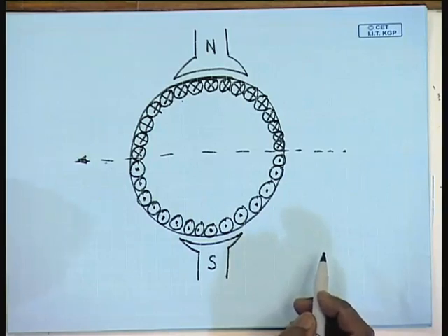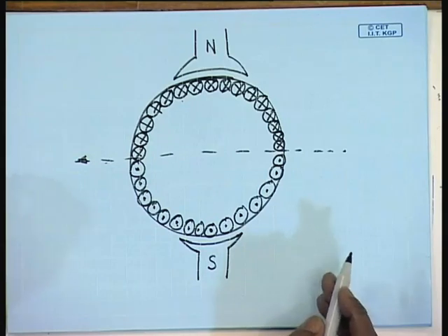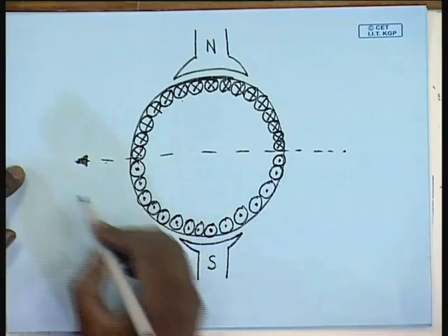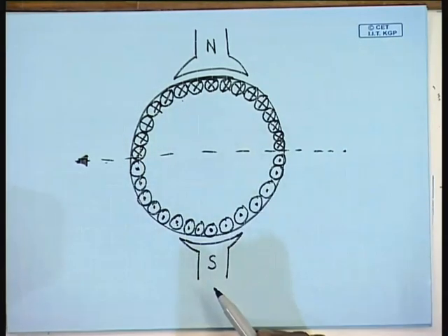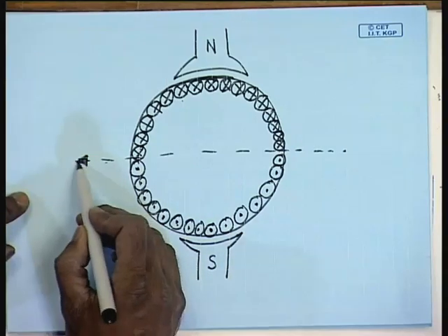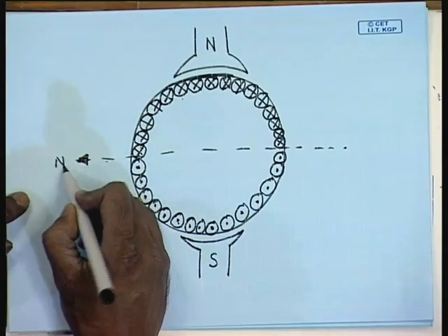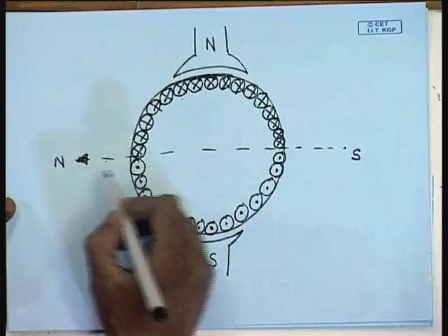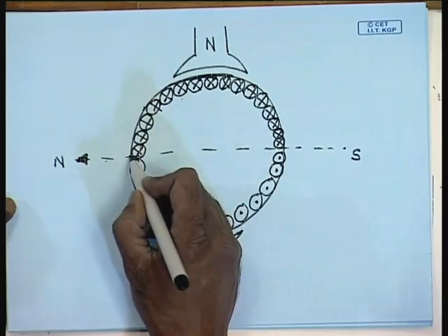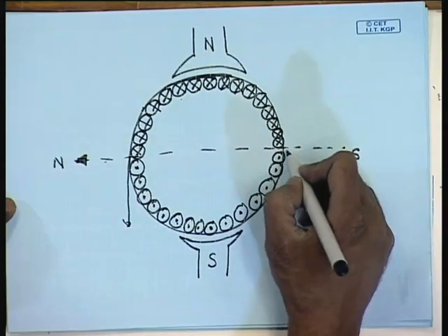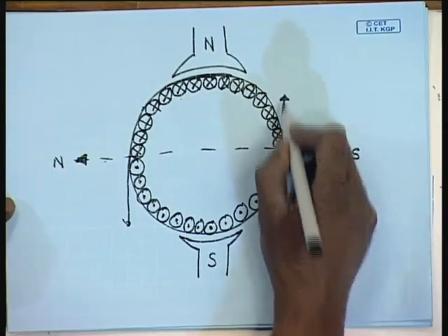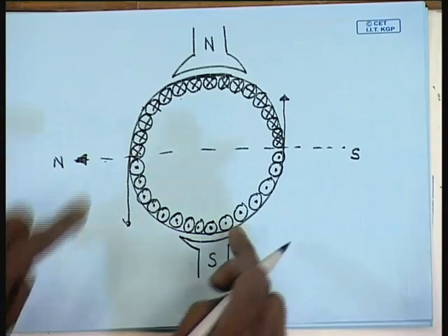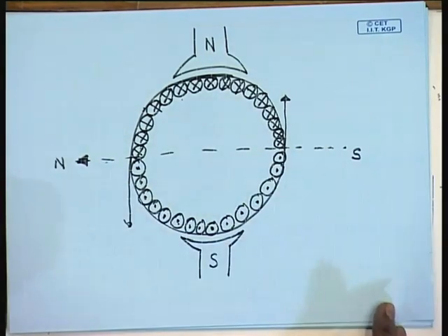But it is important that, now we can extend the principle of operation for this practical case. Let us say at any instant this is the polarity of current. Obviously, this arrangement will still produce a north pole in this direction and a south pole in this direction. Hence, there will be a force of repulsion on this body, and hence a torque will be generated. So, the armature body with all its conductors will rotate.